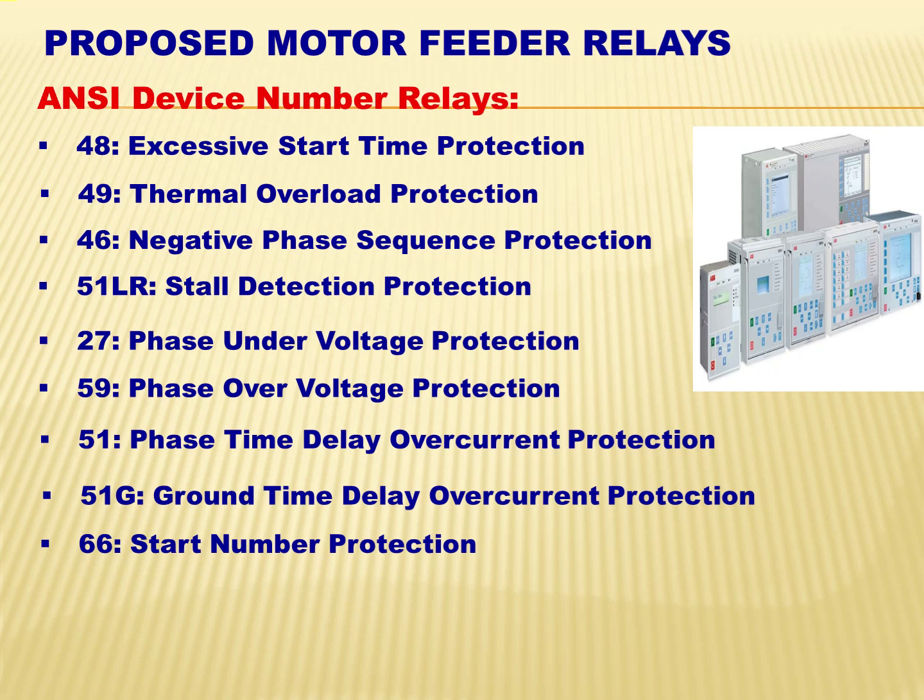A well-specified motor will have a prescribed number of starting attempts, for example, 2 to 5, then a rest period before the same attempts are repeated. The rest period is typically half an hour to 1 hour. This should apply especially to motors that have long starting periods, such as motors that drive high-speed compressors.